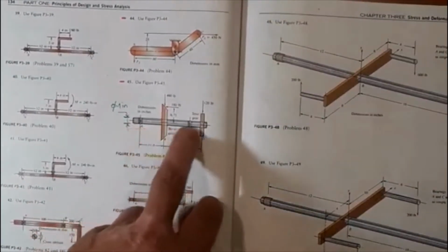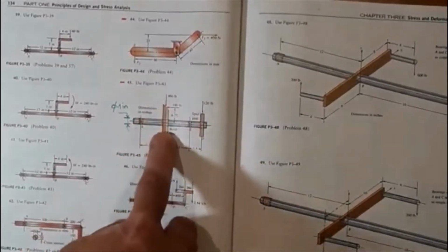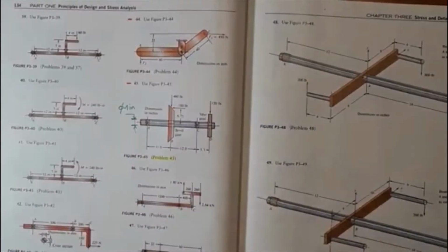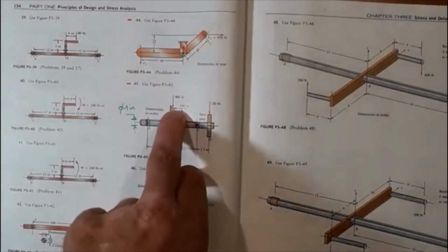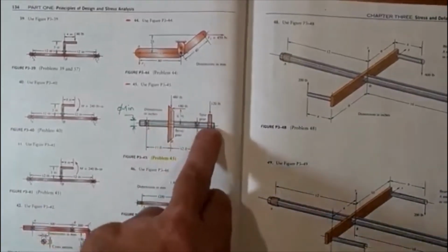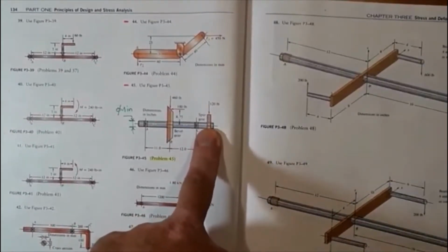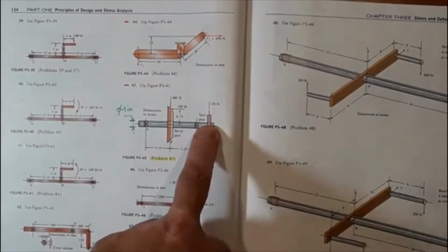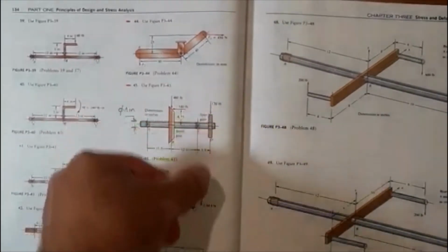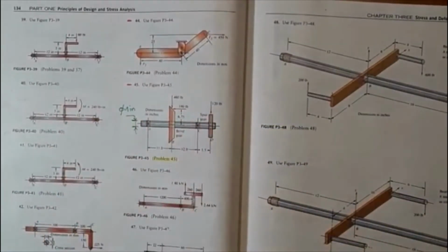cylindrical shaft of constant diameter, and there's a bevel gear, and these are the reactions at the meshing, where the gear meshes with its conjugate gear, with a pinion possibly. And this appears to be another, it will be a straight spur gear, or maybe a pulley. In case of a pulley, the belt would be stretched down, and there's a second pulley, of course, is driving the shaft, or it's driven.